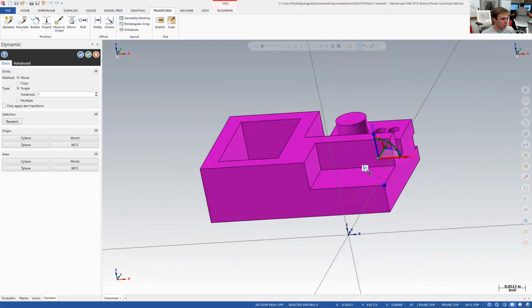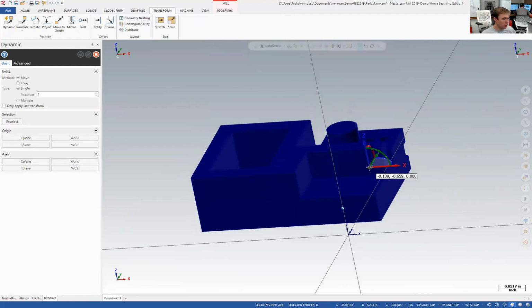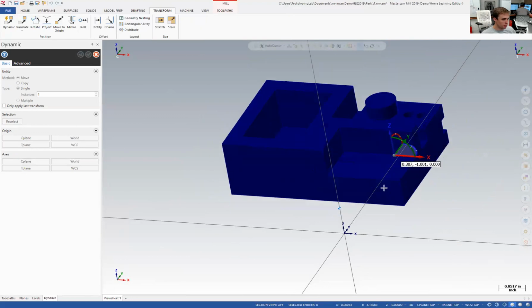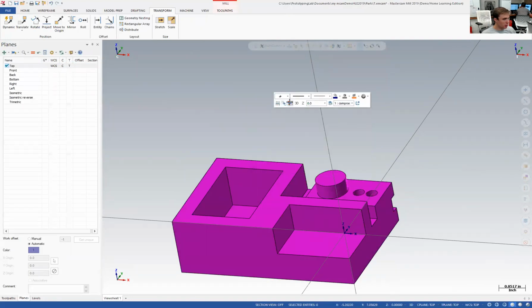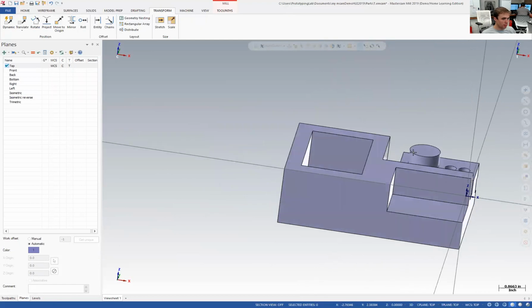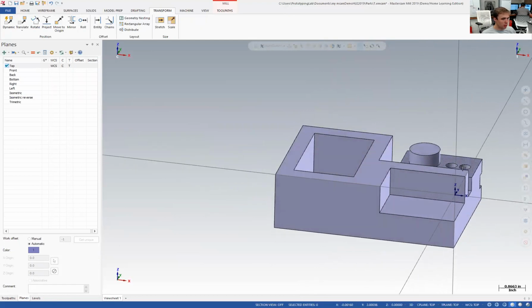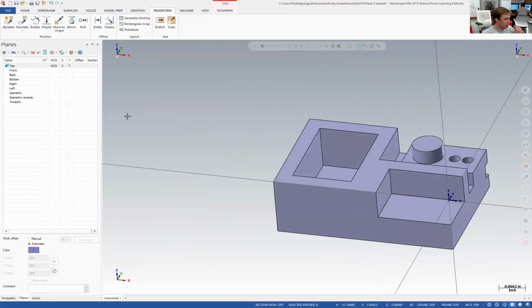Then I can come, punch this again, and now when I move the part, it's moving the part relative to the global coordinate system. I'm going to go ahead and put it down right here and hit green check. I'm also going to clear the colors because I like gray. Awesome. So you can see that it's lined up just perfect on that corner. And if I double check by clicking on the top datum, it's oriented the way that I want.